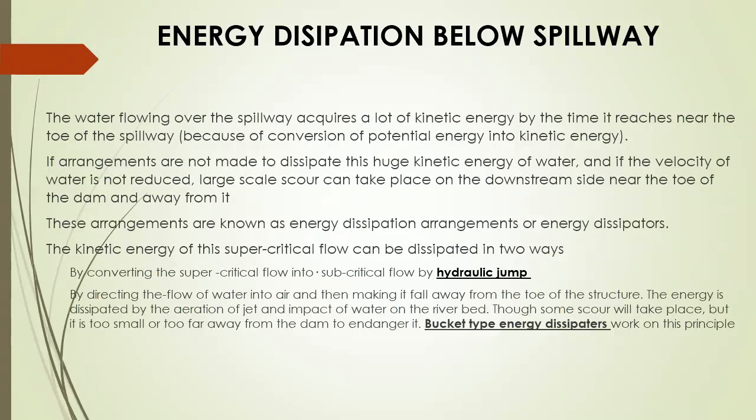If arrangements are not made to dissipate this huge kinetic energy of water, and if the velocity of water is not reduced, large-scale scour can take place on the downstream side near the toe of the dam and away from it. These arrangements are known as energy dissipation arrangements or energy dissipators.